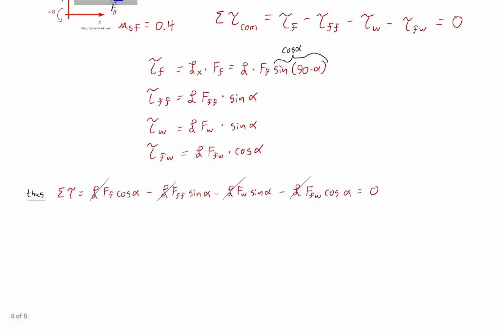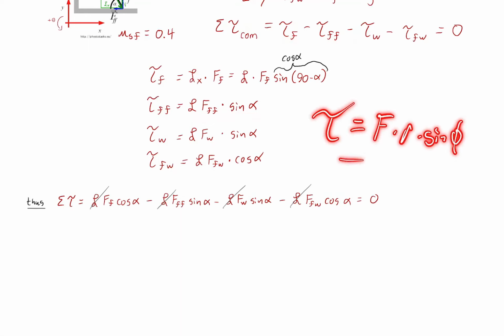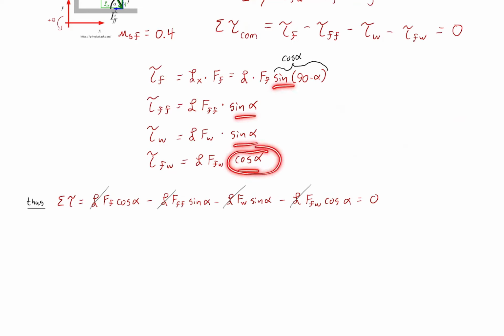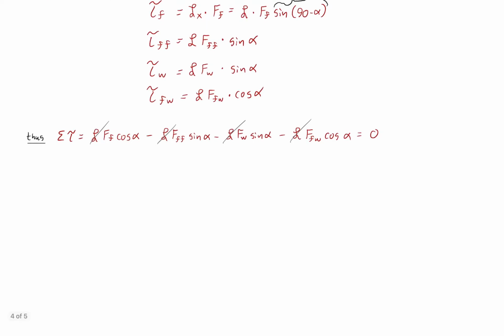And then we go down and rewrite the sum of torque equation. What I'm essentially going to do is express each of these in terms of their definition of torque. And again, it's just using that torque is F times R times sine of the angle between the two. That's all I've done. I've actually used sine in every one of them, all but cosine because it was the component that made sense. And the L cancels out. Remember, curly L is half the overall length of the rod, or the ladder.